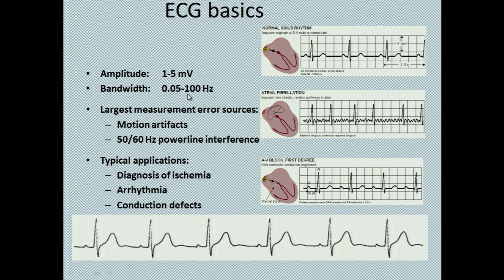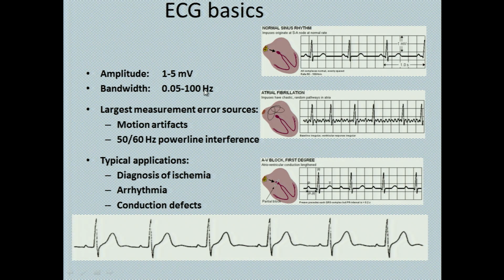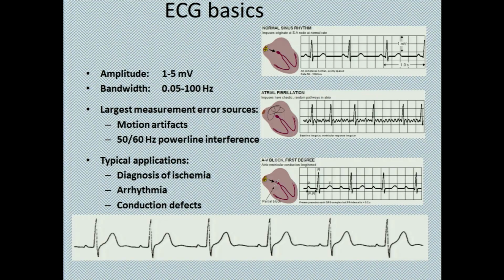So, you can see that it varies so much. If you have to build a band pass filter, you have to filter any frequency below 0.05 and cancel it, and any frequency above 100 you have to leave out. So, we will have one low pass filter which will allow only below 100, and one high pass filter which will allow above 0.05. But remember this 0.05, it can be 0.048 and so on, because our resistor and capacitor values decide finally. And then what could be the error?